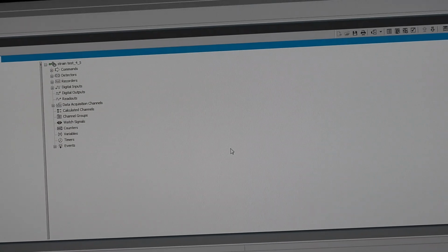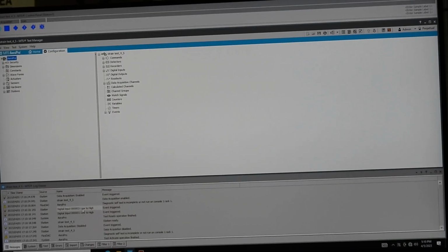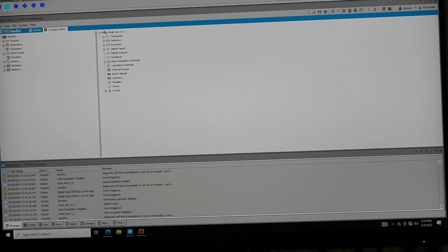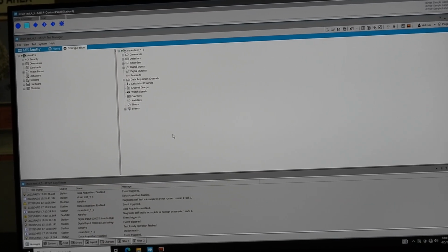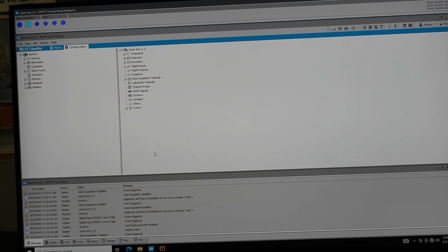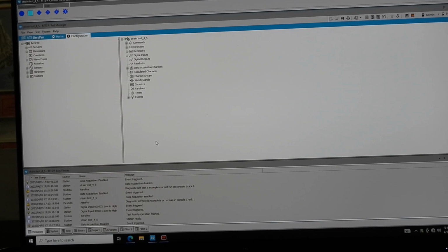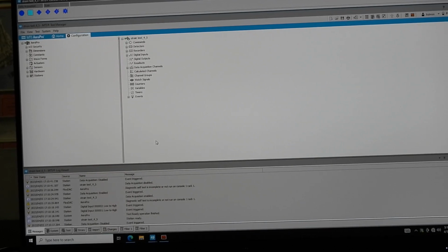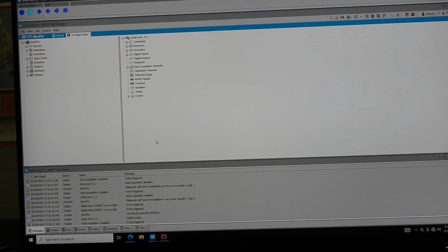Oh, that's interesting. Well, it thinks I started it based on my events. So it saw a low to high on 34, which could be because it's floating. Because if I don't have it hooked up to anything, what's the voltage, right? You don't know, I don't know. I hope it's not fluctuating that much. Well, if it's floating, it could be 1.5 volts, it could be 3 volts, I don't know, right? But that's not a use case.